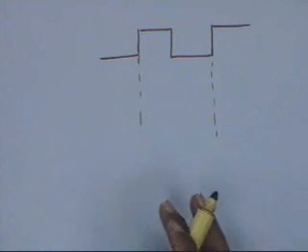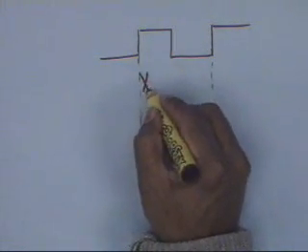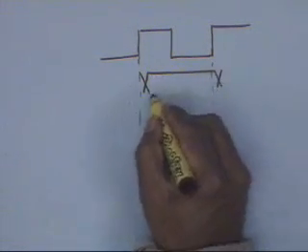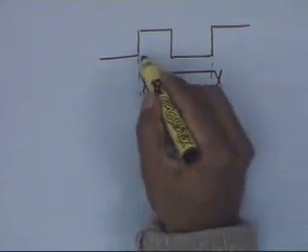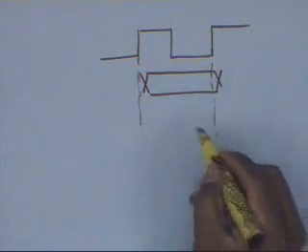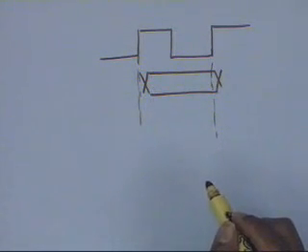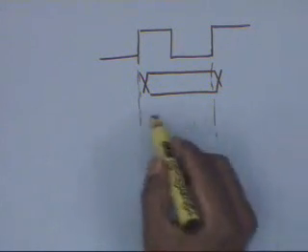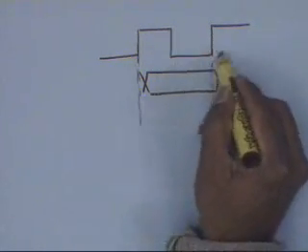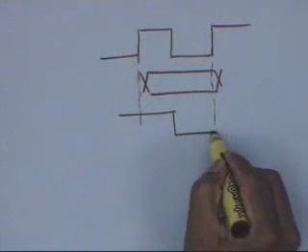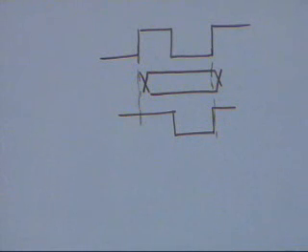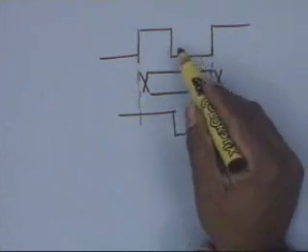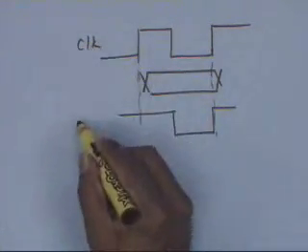Okay, and let me tell you what is the type of logic. Your address is going to be generated over this period. If you are doing a one cycle operation, the address that I am going to write is going to be generated over this. Now, I can generate a write pulse by gating this. But the problem is, as soon as I start gating with this, this is my clock and this is my write.